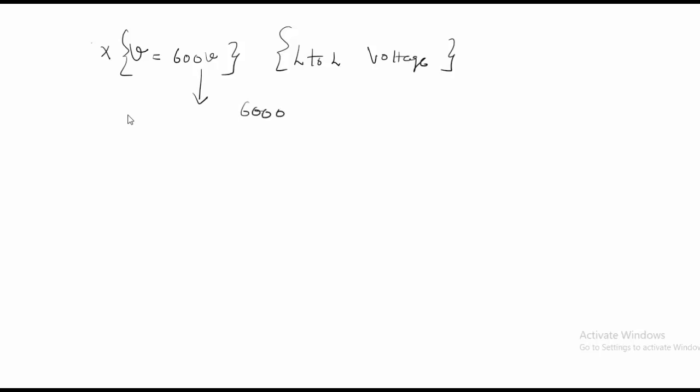So just to summarize, the voltage which I have given is equal to 600 volt. This was my line to line voltage, and when I am converting this to phase, it will be equal to 600 divided by root 3, which is my VPH. Now I had the values based on which I calculated the equivalent impedance, which was again per phase.